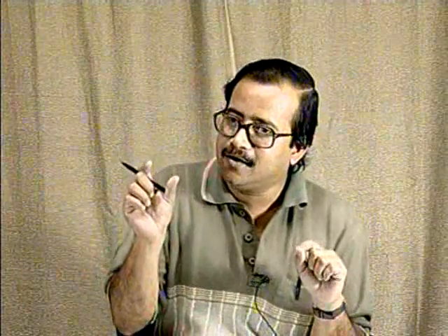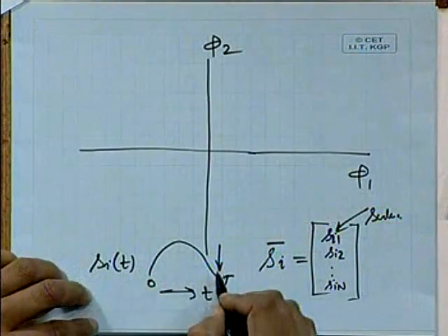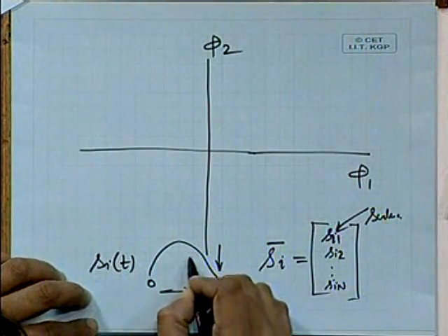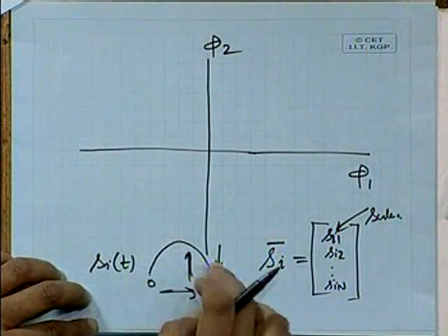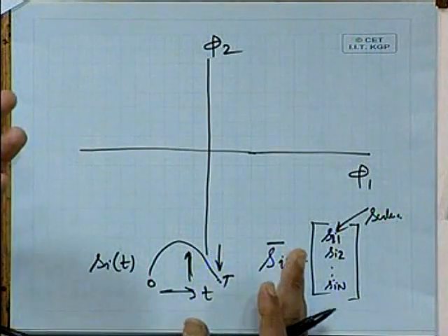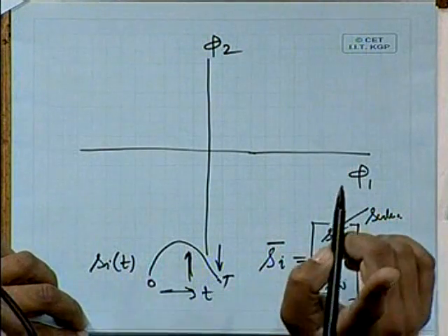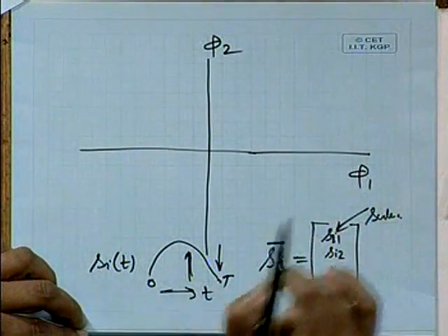But the point is that when you talk about this detection strategy, we will see that we have a fundamental responsibility of detecting or deciding about one symbol when the corresponding Si(t) has been received. See, our issue in the receiver is to decide at this point, not earlier. One should not think of taking a decision midway in between, unless there is some special reason really, and that decision is not going to be best perhaps. So the decision has to be taken once in capital T duration.